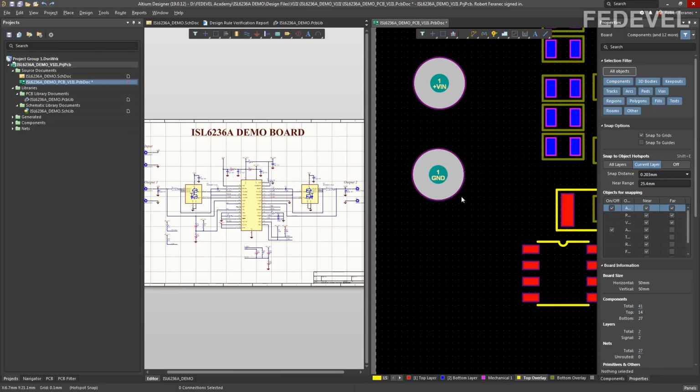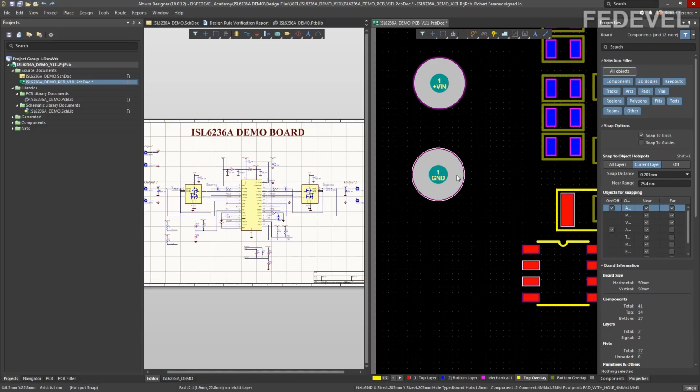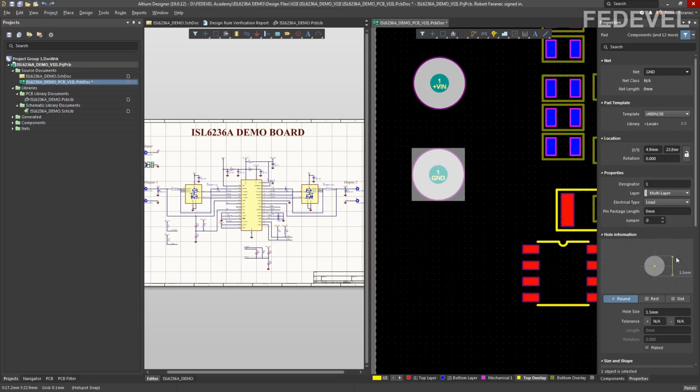Yeah? If I left click somewhere here, this is again selected, but this time this properties menu looks different. See? Now the J2 component is selected. Watch again, okay? I'm going to left click into empty space. Remember how this looks. And I left click on the path directly. See, this is different. These are properties of the path. If you change the location here, then you will be changing location of the path.